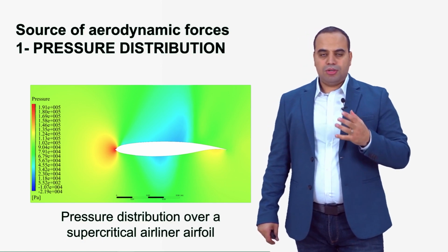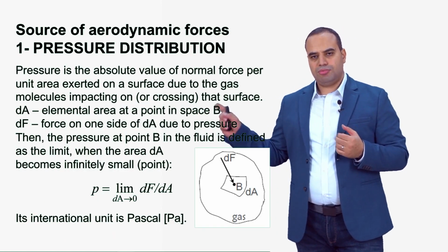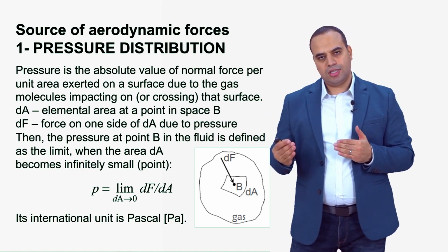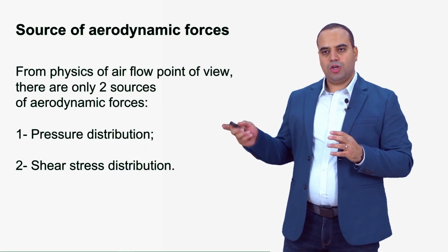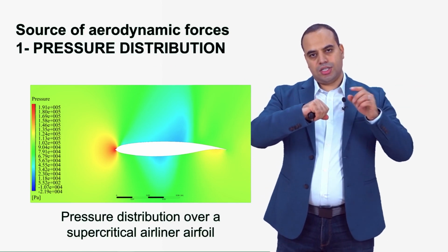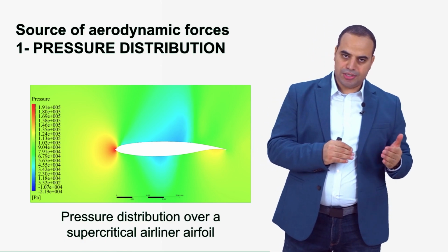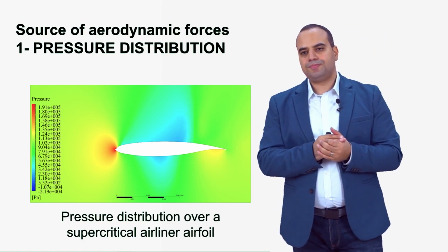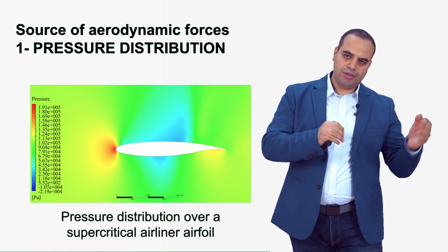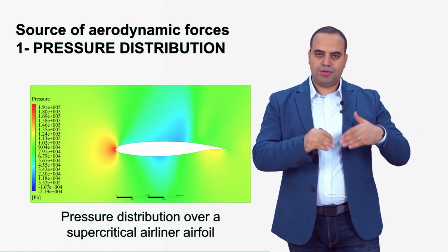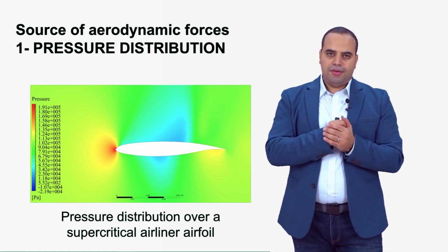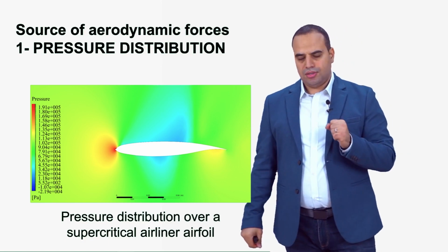The Bernoulli law, or the Bernoulli equation, links the pressure with the velocity, right? And the Bernoulli law says that with increasing velocity, the pressure drops, and the opposite is true. The opposite, in fact, happens on the leading edge, because there the air particles stop, so their velocity is reduced and therefore their pressure is increased, right? So the relationship between the velocity and the pressure is an opposite relationship: when the velocity drops, the pressure rises, right? And the opposite happens on the top surface of this wing, where we have an acceleration of the flow and therefore a reduced pressure, right?